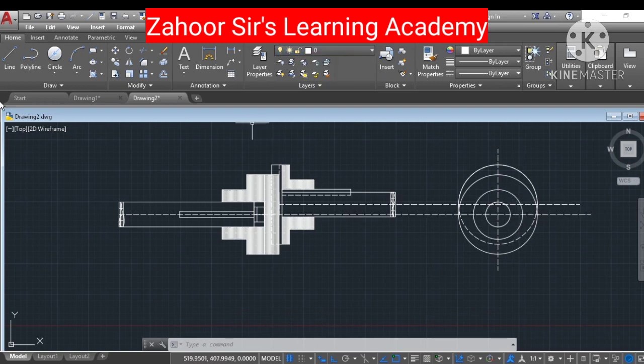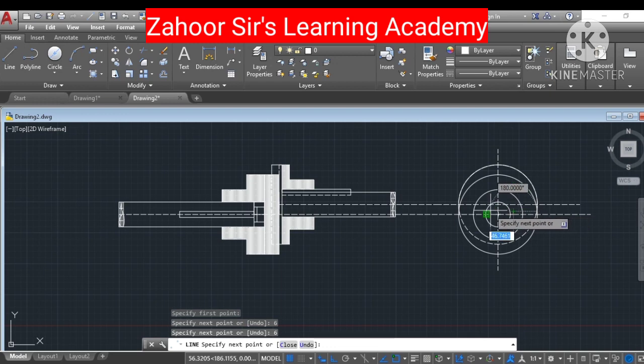For that, again the line command, and from this point we need to go to the left 6 mm to show the key, then press enter, then up 6 mm, enter, then inside how much, 12 mm, because it is a square key, then down 12 mm, enter, then again 12 mm, enter, then up 6 mm, enter. Then escape. So this is how you can draw the key.